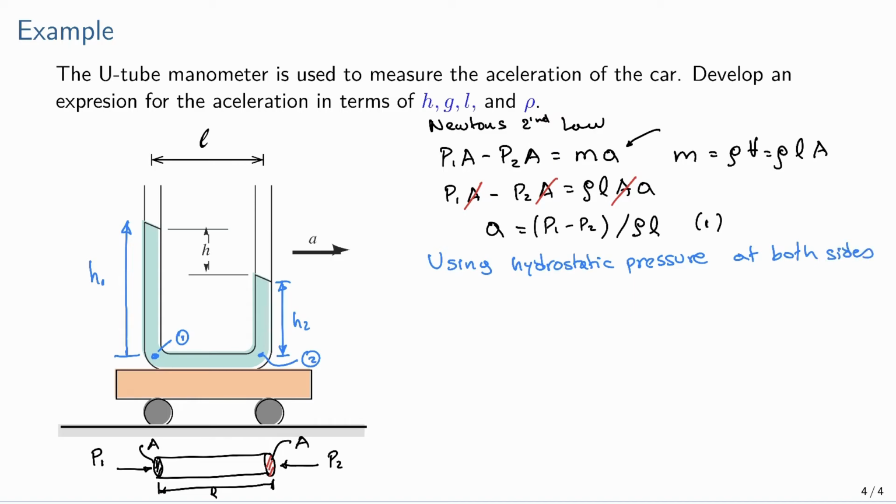we have that P1 is equal to the pressure at the top, and the pressure at the top is equal to 0 if we consider atmospheric pressure and manometric pressure. So P1 is that pressure plus the weight of this column. So that's it. Atmospheric pressure, which is 0, plus gamma multiplied by H1.